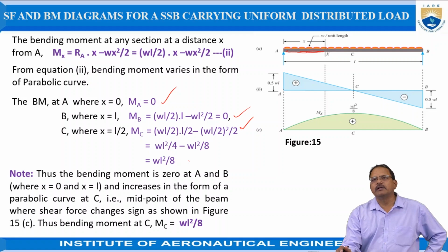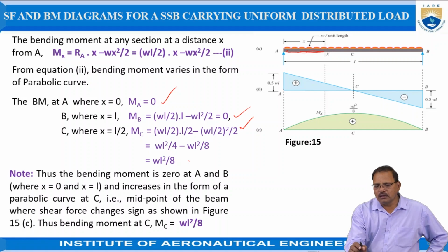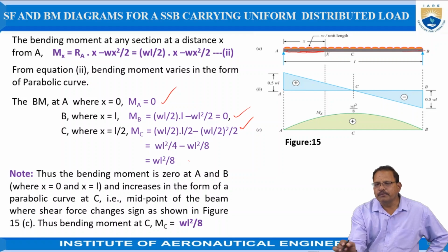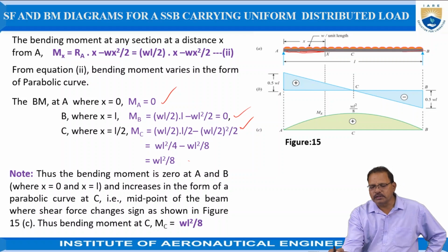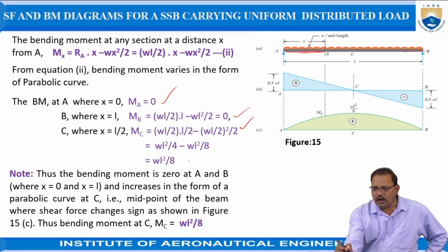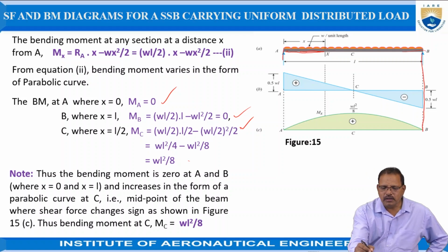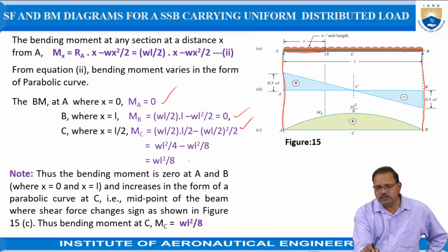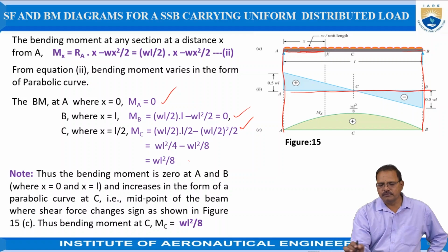The procedure for drawing the shear force and bending moment diagram is, first of all, draw the beam according to the required scale. Here, draw the line and represent the uniformly distributed load over its length as shown in the figure. After that, draw the vertical lines passing through points 1 and 2. Now, at a convenient distance, draw the lines which represent the length of the beam.